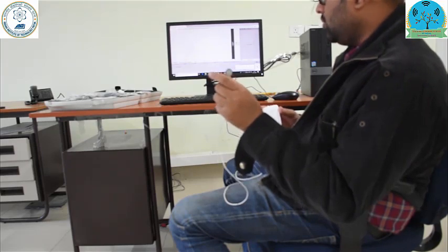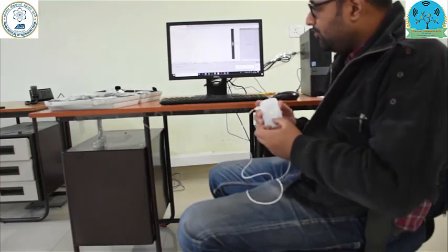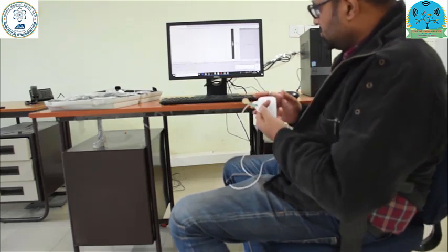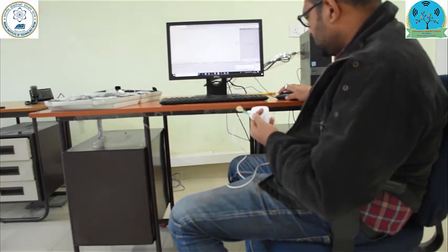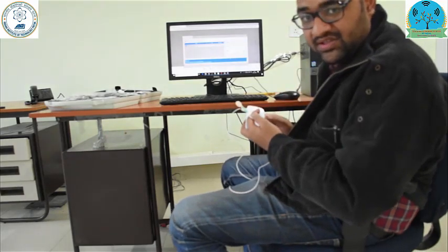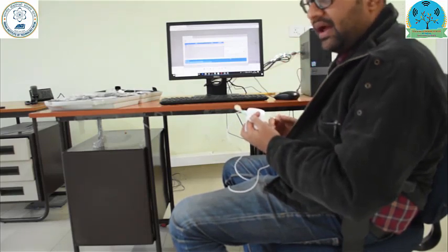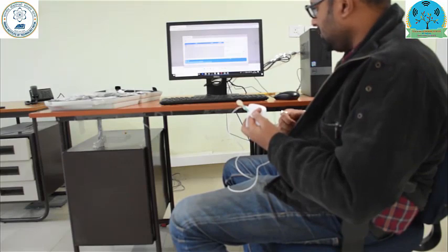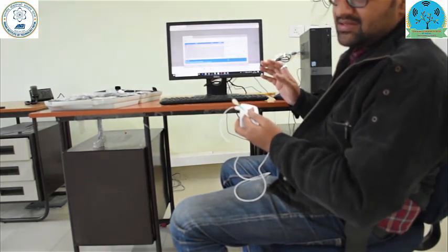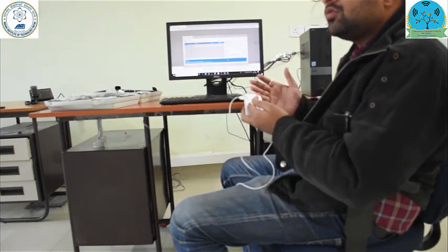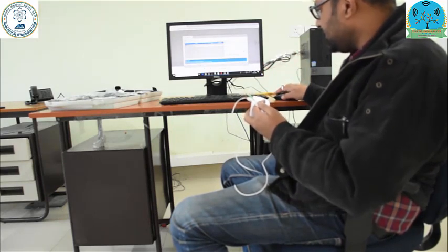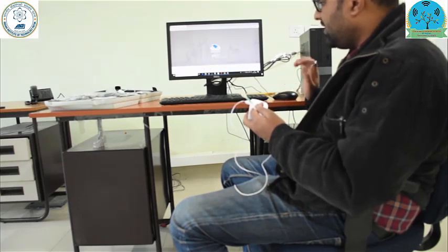Now, once it is recorded, a very important task for any biomedical analysis is to save the data in the right form. This tool allows you to save the file in 3 different formats, which are .txt, .h5 and .edf, European Data Format. Hence, we can save this file on our system as well as on the cloud. For the cloud, you might have to get access or purchase storage. But to store the file on your system, you just click the Save As button, it asks for the name, and the file gets saved.